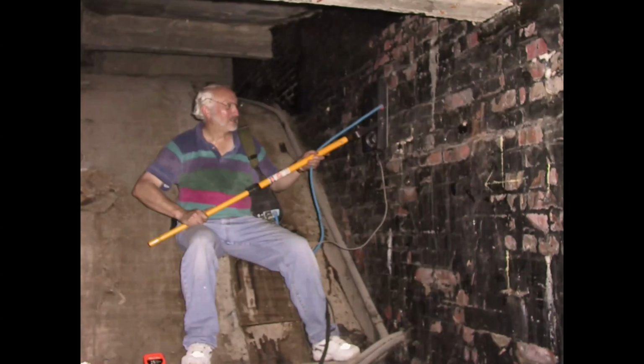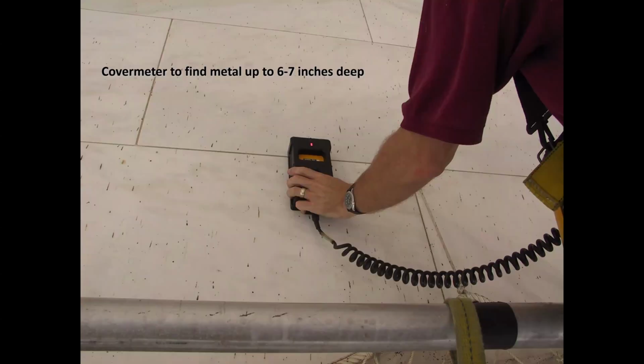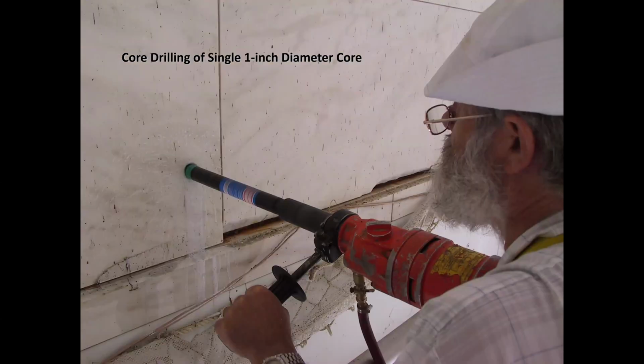We also did some scanning down below in some masonry walls, brick masonry that were inside, checking for metal there. We did a cover meter, which can check up to 6 to 7 inches deep. We tend to do a lot more GPR, ground penetrating radar, to find steel because it tells you more. But modern cover meters can estimate the bar size. But if you had bars, obviously not here.